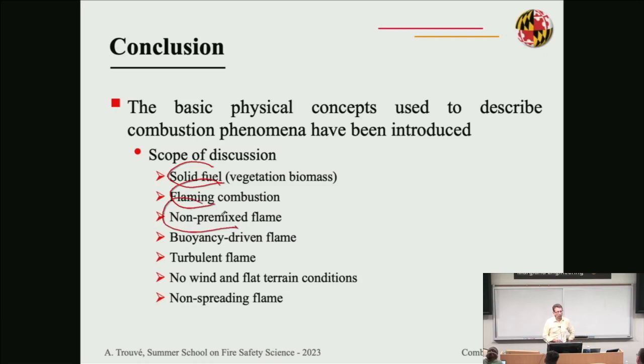We consider that the dominant mode of combustion is non-premix flame. That hasn't been disproved yet, but there are premix flame combustion aspects that are important for ignition, and Sarah McAllister will talk about that tomorrow. Our flames are buoyancy-driven, which makes them a little bit unusual. Most of the combustion science literature is focused on momentum-driven flames for engine applications. So sometimes we have to really explore the new physics associated with buoyancy-driven flames.